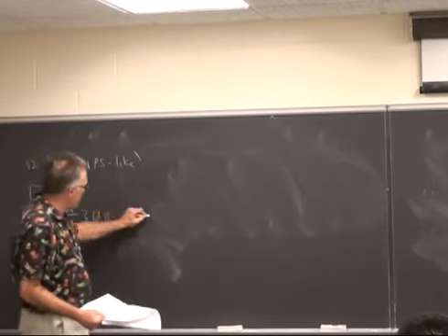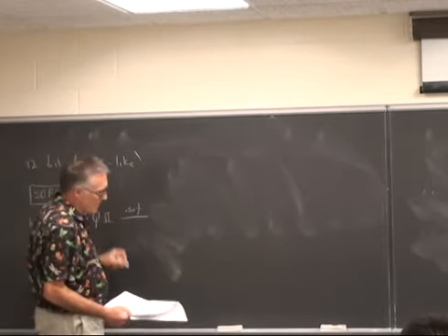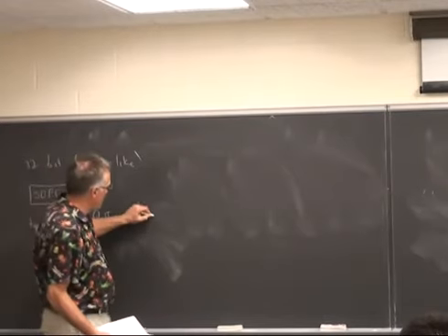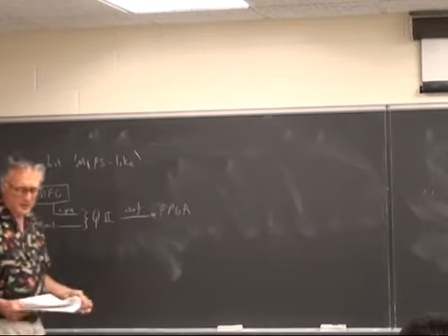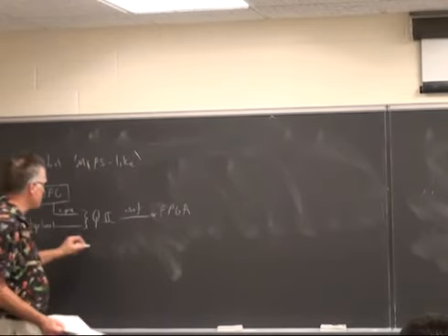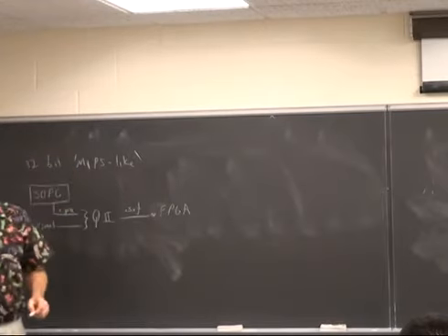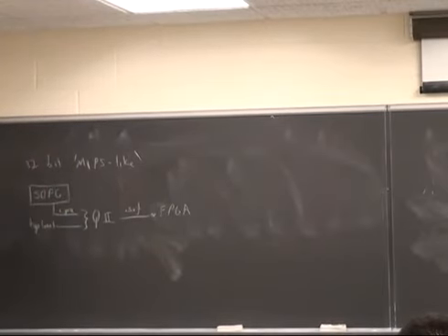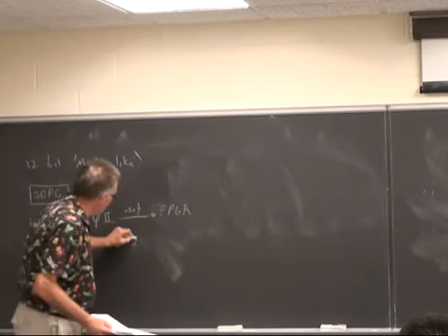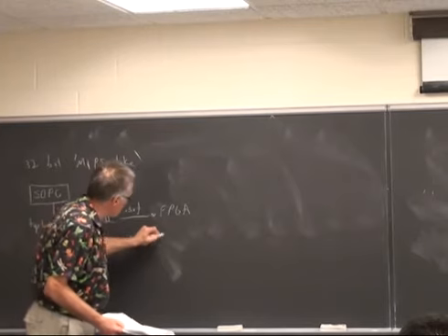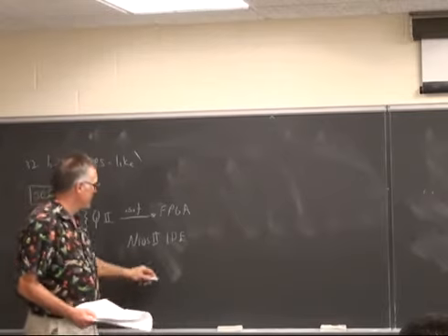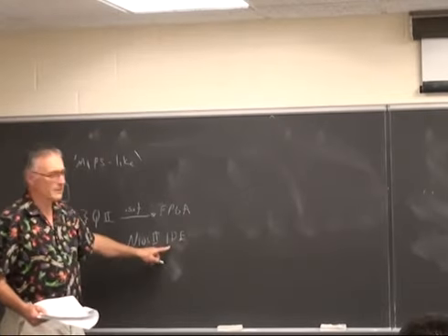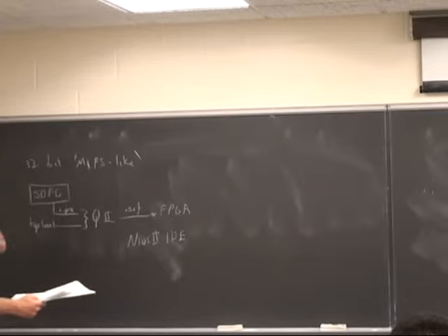And then out of that is going to come an SOF file, which you're going to download to the FPGA, and that's going to have the description of the CPU. But then you, of course, also have to write the C code. And there are now two different ways of doing that. One is the NIOS 2 IDE, Integrated Development Environment. This thing's a monster, but you can do whatever you want with it.